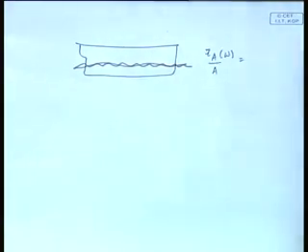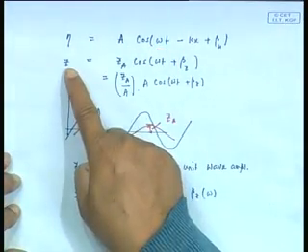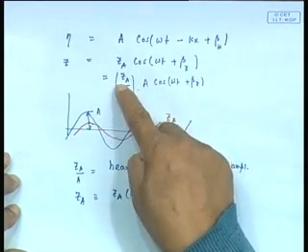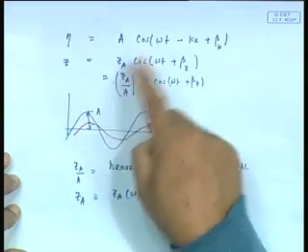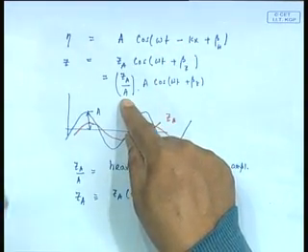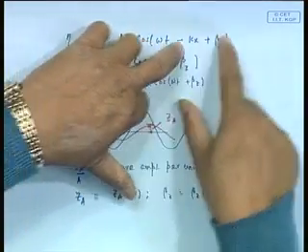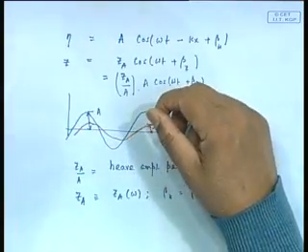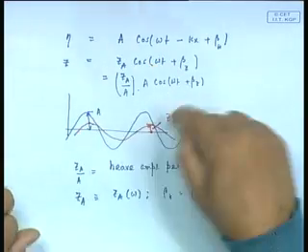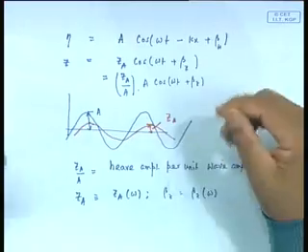Okay. In other words, what is happening is that for a given wave of frequency omega, I have an output heave of amplitude ZA and phase beta Z. Obviously, the output depends on the input. Number one is that output per unit of A remains constant, because as far as A is concerned, if I have eta 1 equals A1 cos omega t, eta 2 equals A2 cos omega t, I can add A1 plus A2. Amplitude can be added at the same frequency, but wavelength-wise obviously the response will depend on omega. So therefore, ZA by A is a function of omega. Naturally, different wavelengths would give you different response. This is exactly what we have done.